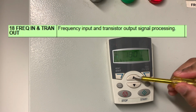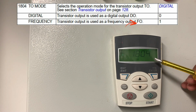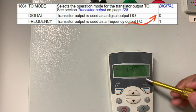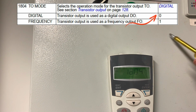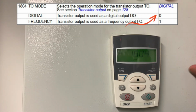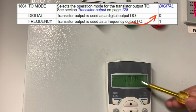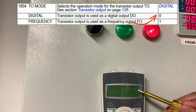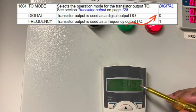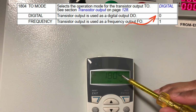In parameter 18 go to parameter 1804. In 1804 you have to set whether you want to use that transistor output as a digital output or as a frequency. If you want to make it a digital output, you have to make it 0, otherwise you have to make it 1. So in this case it's 0. 0 means I want to use this as a digital output, not as a frequency output.